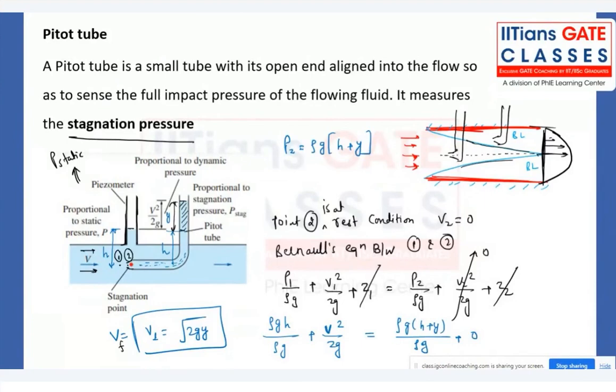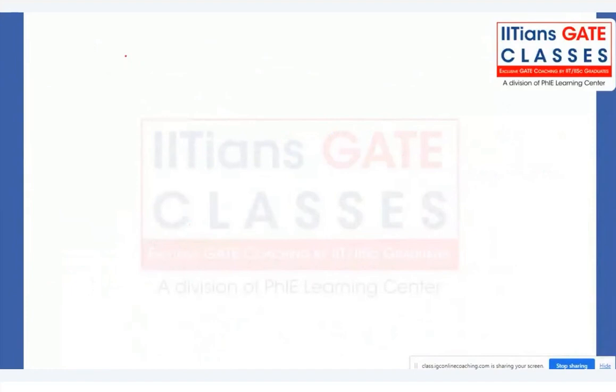Generally, some of you might be thinking, sir, we can directly see with our own eyes the height it has been raised, so why the need of a piezometer? No, you will see directly the total height which has been raised from here to here. Now, how to subtract this particular height? When you place the piezometer, you can see the height reading of the liquid raised in the piezometer, and that we subtract from the total pressure, right? So what we are actually doing here is writing total pressure as stagnation pressure, right?